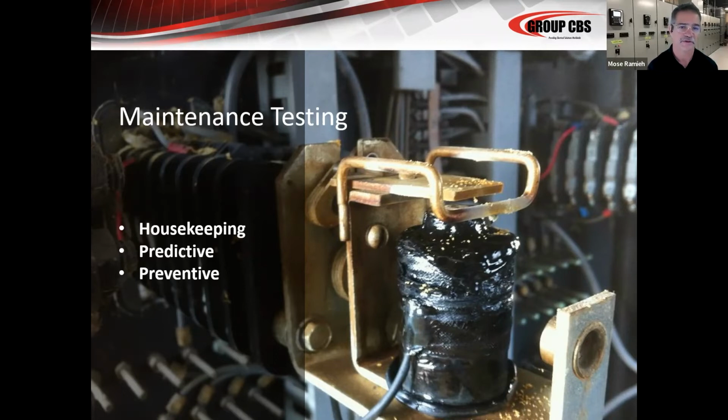And this particular 86 caused a catastrophic, or, I shouldn't say caused it, it was the weak link in the chain, and caused a piece of 15 kV switchgear to basically literally burn to the ground until the utility finally was able, utility relays were finally able to clear it. And so once again, each one of these components is super critical to be checked.